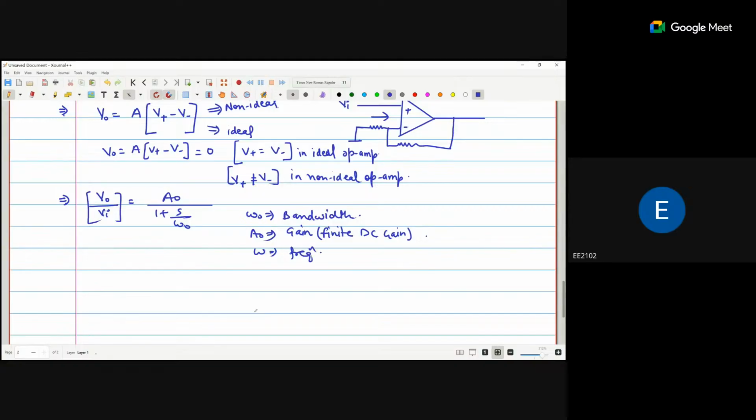As we put s equal to j omega, V naught upon Vi is A naught upon 1 plus j omega upon omega naught.